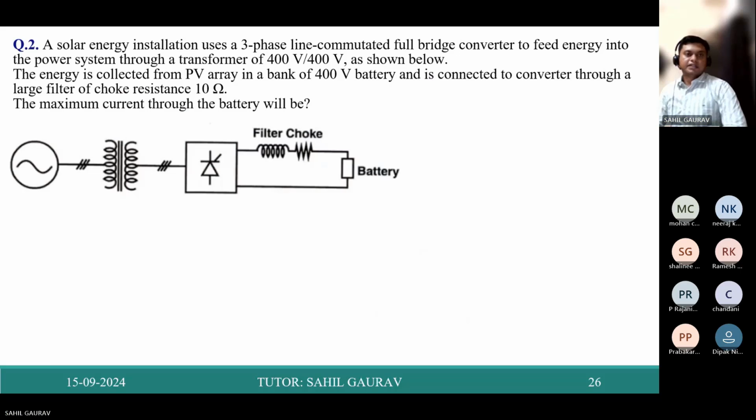Here in this problem, a solar energy installation uses a three-phase line commutated full bridge converter to feed energy into the power system through a transformer of 400 volt, 1:1 as shown below. The energy is collected from a PV array in a bank of 400 volt battery, connected to the converter through a large filter choke with resistance. So this resistance value is 10 ohm. The maximum current for the battery will be...